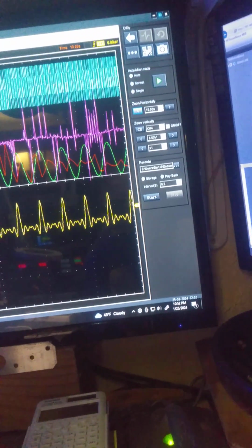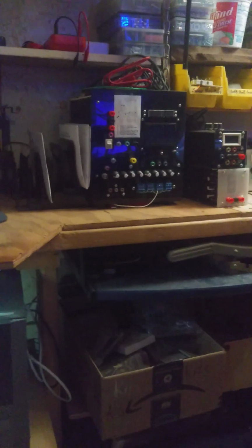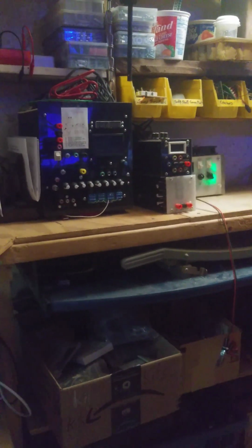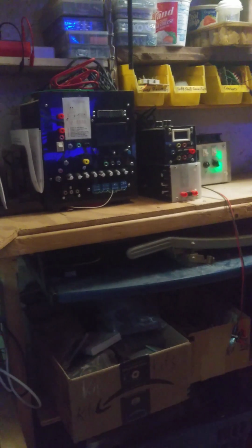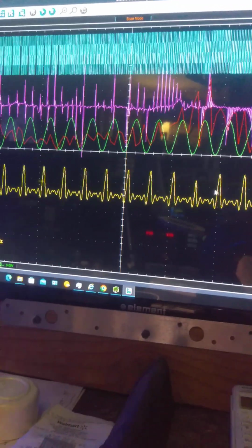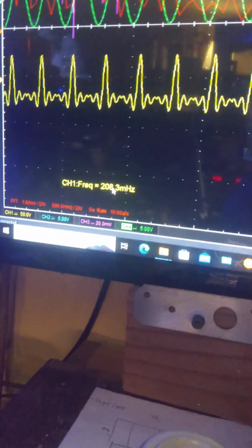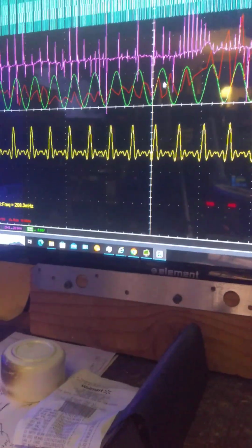So, this thing apparently does change its sampling rate significantly with your frequency setting here, which doesn't surprise me. It's kind of similar to a little piece of test equipment I built over there, which does the same thing, just not at as high a frequency. It's an 8-channel too, but it was a great example of Nyquist and how even at fractional frequencies, you can generate phantom signals. These are both phantom signals, but yet they keep the characteristic of a pure sine wave, even though it thinks it's only like 200 millihertz. When it's 10 kilohertz, both of these are 10 kilohertz signals.